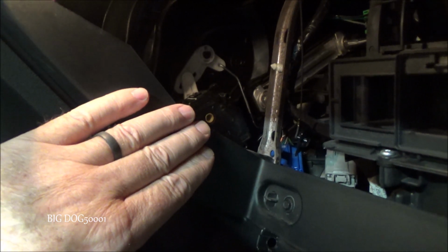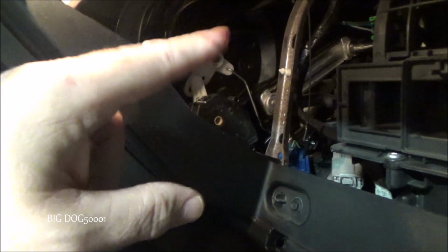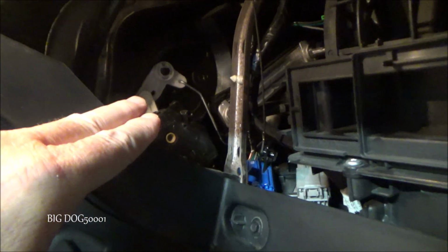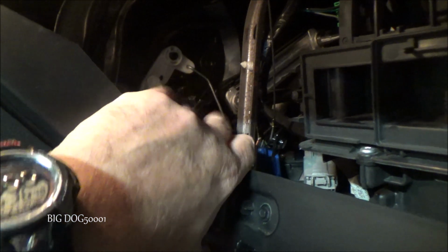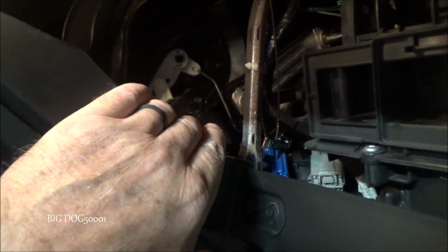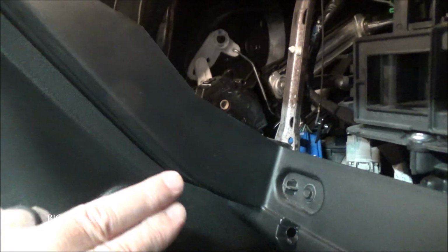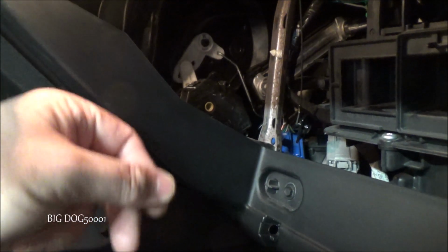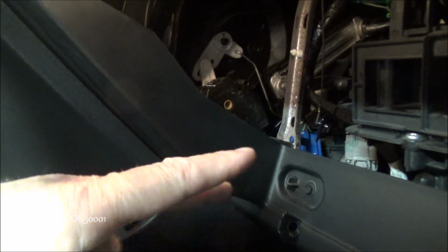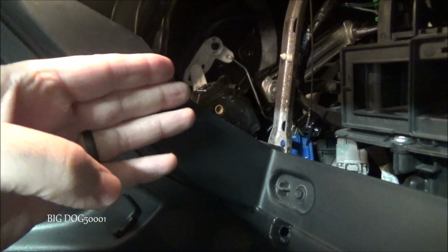When I did it before, what happened was I would change the temperatures. I tried it on here, and I tried it on a scan tool, and it didn't matter, nothing would move. And then I did my old tap test. I tried tapping on it, nothing changed. And then I was kind of worried that maybe we have a broken wire or something, so I unplugged it, and then I commanded it with the scan tool, and of course it didn't move.